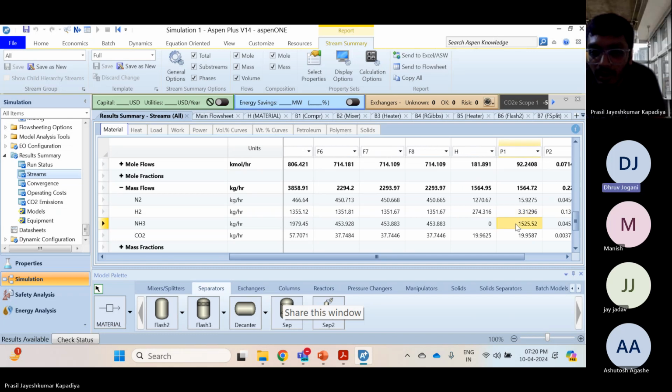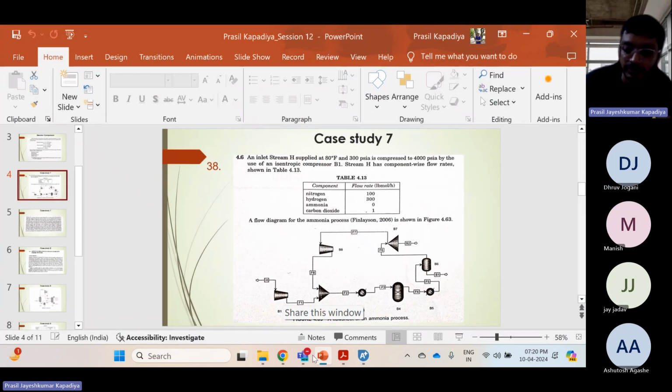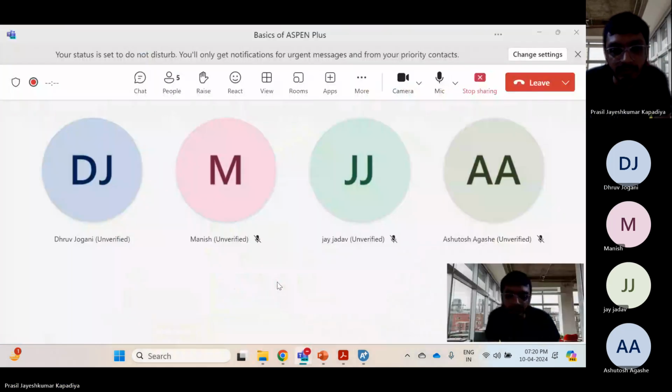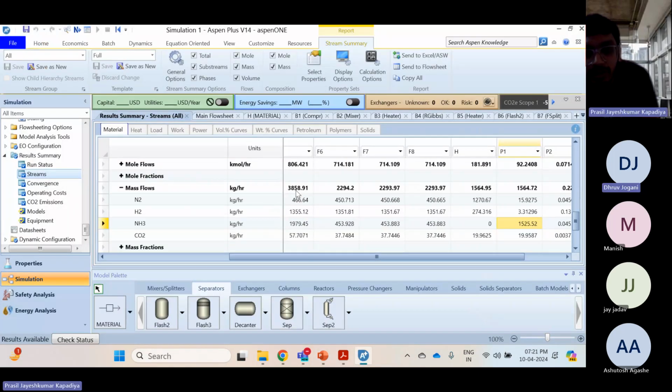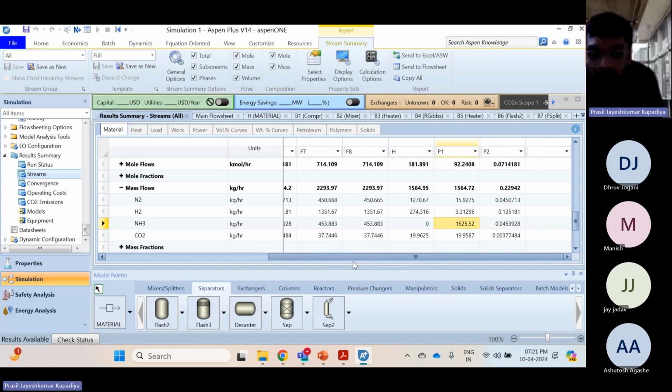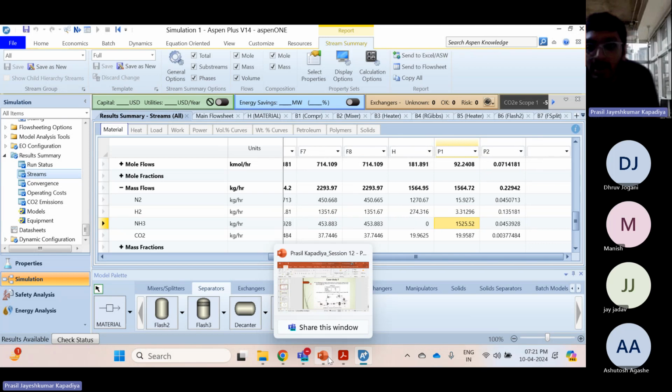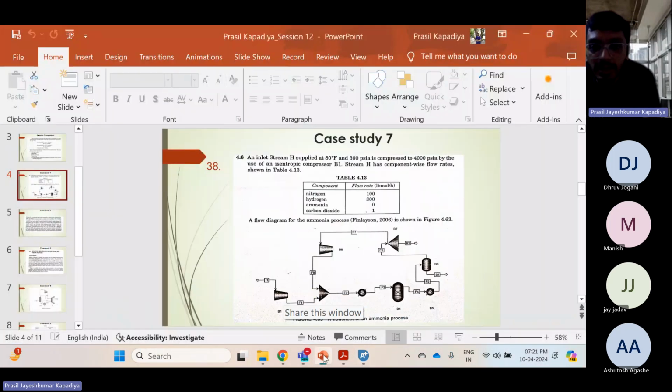Wait, sir, I'll check the results of stream P1. Yes, sir, 1525.52. Okay, so we are getting the maximum amount of ammonia from here, and whatever N2 and H2 is not reacted, we are giving back to the recycle stream after compressing.